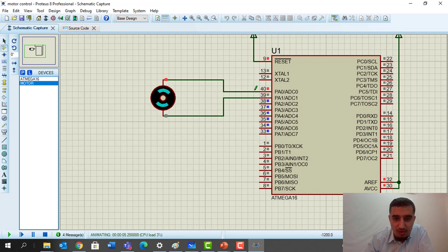It's very, very slow, and it's not enough to move the motor. You can see here. Why? Because the microcontroller does not have enough power to move this motor. It is moving, yes, but as you see here, this is gray. Gray means not enough power. It's not high or low. If it's low, it will be blue. If it's red, if it is high, then this one is supposed to be blue. You can see here that we cannot drive a motor from a microcontroller.